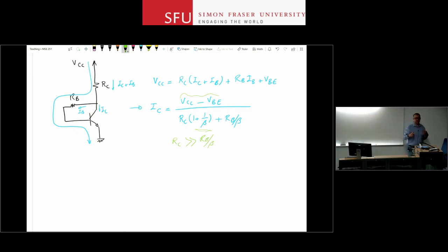But let's see again, from the engineering sense, what happens here. What is causing this behavior? What is making this circuit more stable, less sensitive to those changes in parameters in your circuit or around your circuit? So again, assume that we have established the desired biasing point here for this circuit, and for some reason, IC goes up. Why does it go up? Again, your beta has increased or your temperature has increased.